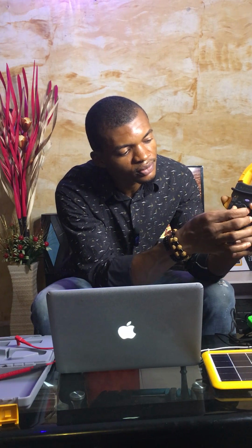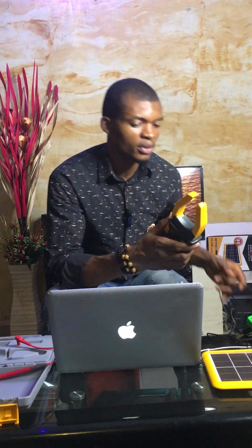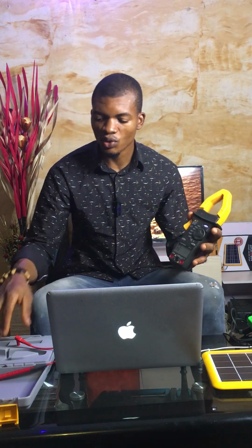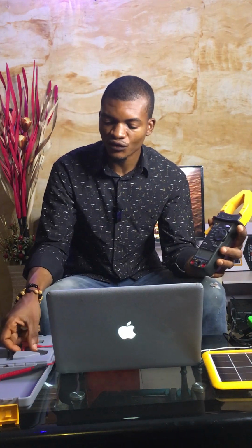Above 200, you can get it to 1000, which is the maximum current that this particular multimeter can handle. And remember that in measuring the current, you only use the clamp side. You see how open it is? So you measure it by passing the cable in between. In the same way, if you want to measure the voltage,